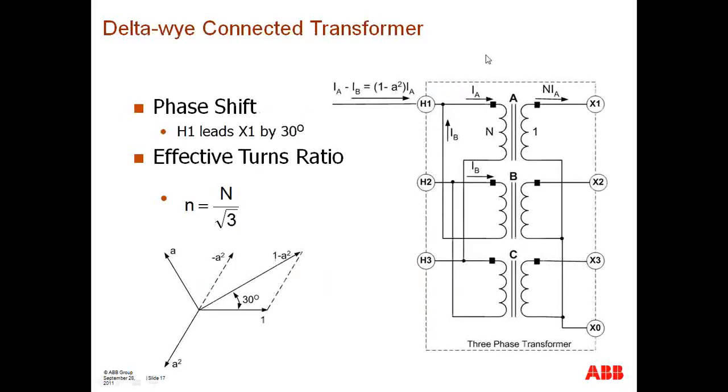So, for a particular distribution substation, you have a 138 to 13.8 kV transformer, 13.8 kV being a distribution level voltage, and this transformer will provide the transformation from a higher voltage to a lower voltage. The Y connection is on the distribution side, so there's a healthy source of zero sequence currents, so that phase-to-ground faults, or faults involving ground, can be easily detected within that network. This is a very, extremely common arrangement utilized here in the United States for our distribution systems.